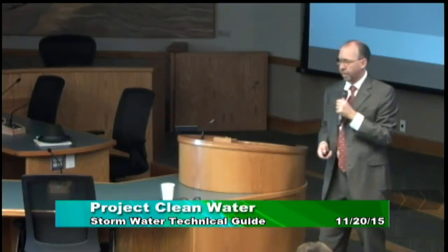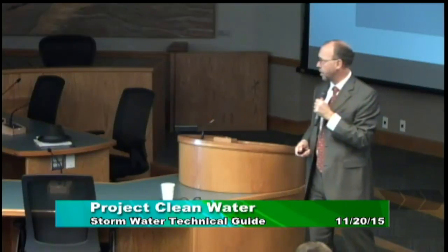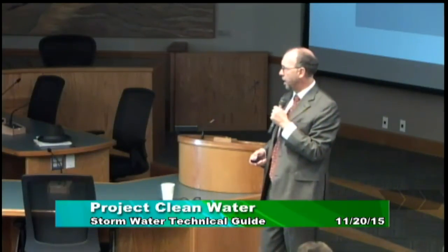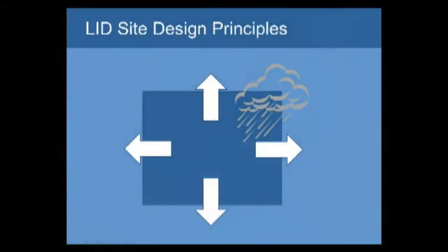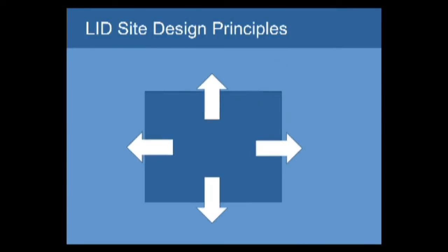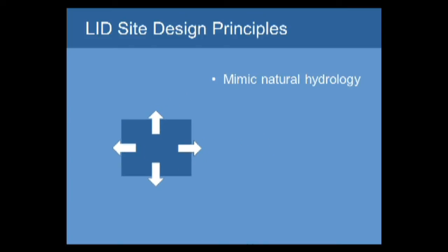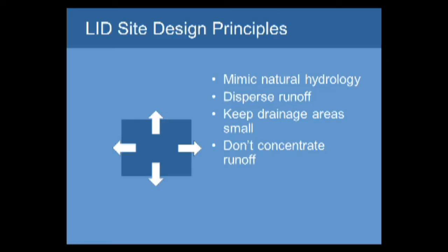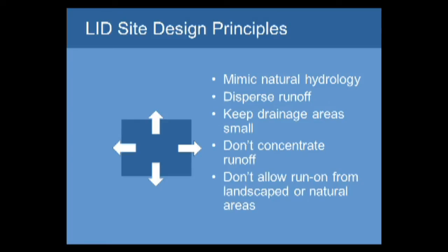This concept of drainage management areas starts from LID site design principles. We want to disperse runoff rather than collect and convey it. We don't want to concentrate runoff. We want to keep our drainage areas small. I had a conversation during the break. That often means you end up with a lot of drainage management areas, which just gives you something you have to manage, and Tony will show how that's done with the calculator.